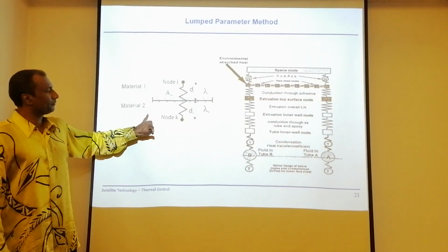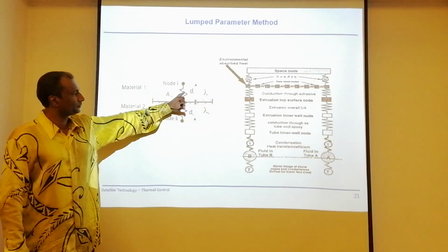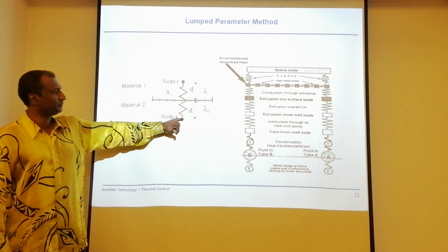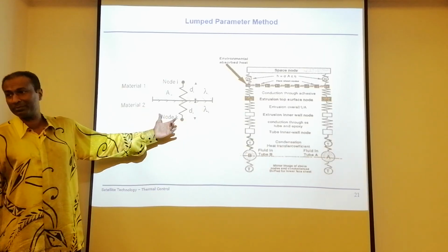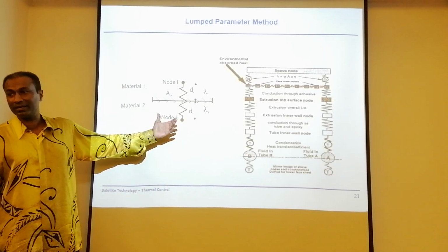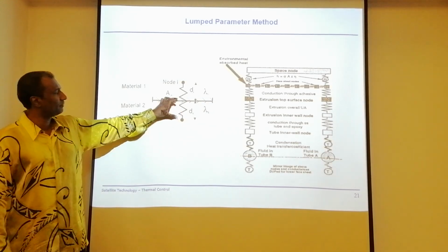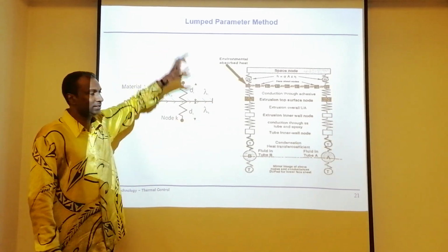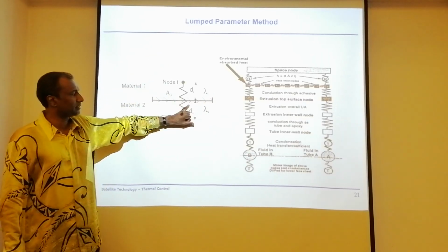So if I treat this as a spring, this is basically a series spring. Technically I can use the same law that we have used in electric circuits to calculate this heat transfer. So you can have layers after layers, depending on lambda 1 up to lambda k and thickness.